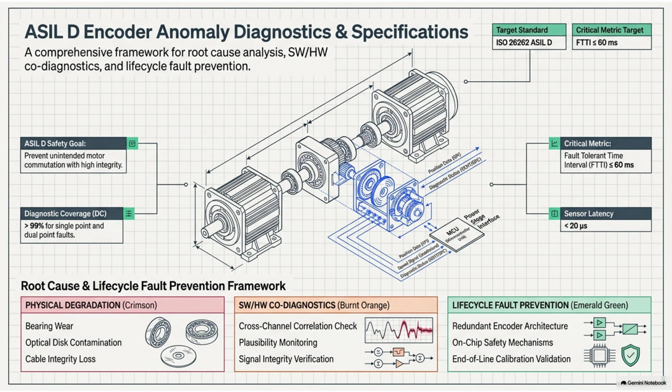The spec actually mentions temperature swings from negative 40 degrees Celsius all the way up to positive 150 degrees Celsius. And that differential in thermal expansion creates just immense mechanical stress. I can imagine. Yeah, and when you couple that rapid temperature cycling with the high-frequency random vibrations of a moving vehicle, which range from like 100 to 1,000 hertz, that delicate glass disc is highly susceptible to developing stress microcracks. Wow, just from shaking and heating. Right. And in extreme cases, it can shatter entirely.